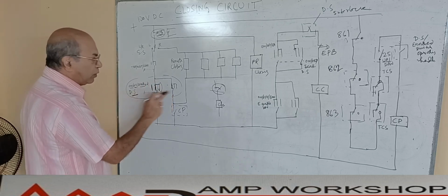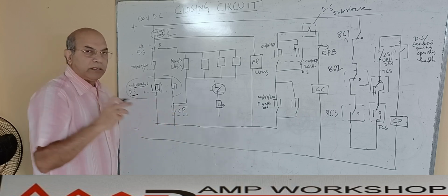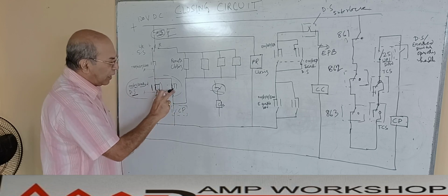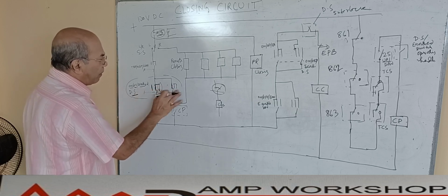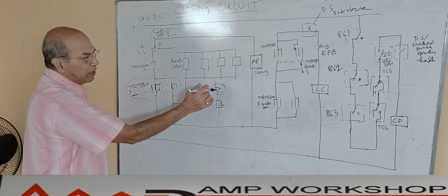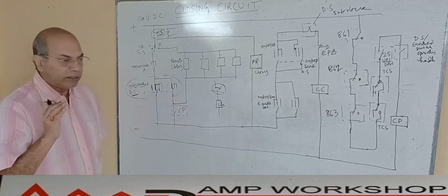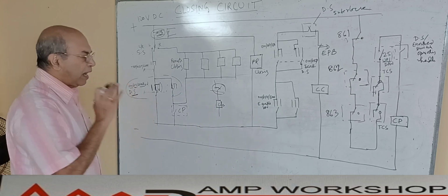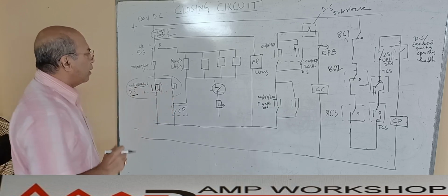So this path is also through. In both cases, whether the isolator is off or isolator is on, or in the case of drawout type breaker, where the breaker is in connected position or breaker in test position, in both cases this logic is maintained either through this path or this path. So this is the isolator interlock in the closing circuit. Before closing the breaker, I have to make sure the isolator interlock is satisfied, that is why I am doing it through this.